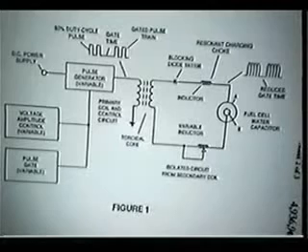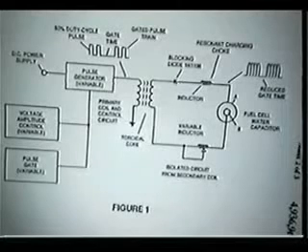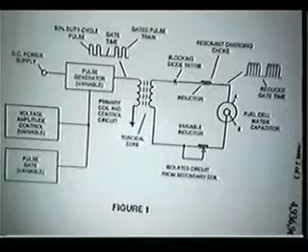The resonant chokes are specifically to damp the voltage spikes that could prematurely set this thing off. So what he's doing is he's making sure that he can charge this capacitor with kind of soft pulses and pulse the thing up so he can get this capacitor to charge to the maximum degree before the dielectric material, in this case water, creates a catastrophic dielectric failure in the capacitor.